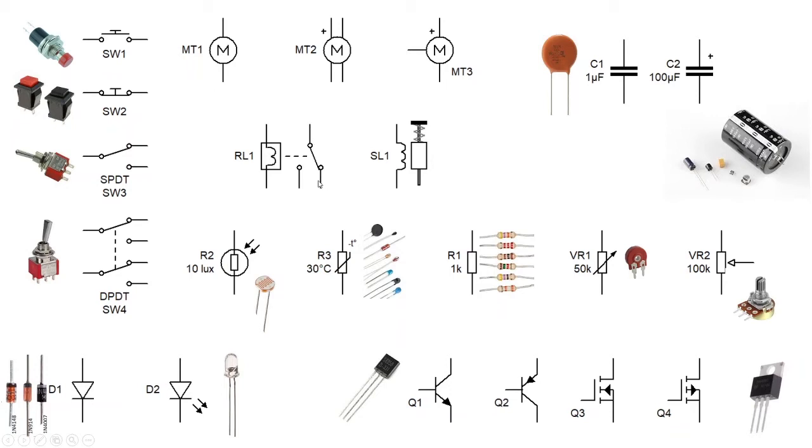So if you've got a tiny microcontroller with a tiny output current, and you want to switch on, say, a mains voltage, what you might use is a combination of amplifying that switch. You start off with a little transistor, which is capable of energizing this coil, which will then switch on a much bigger switch like that, like a mains voltage.